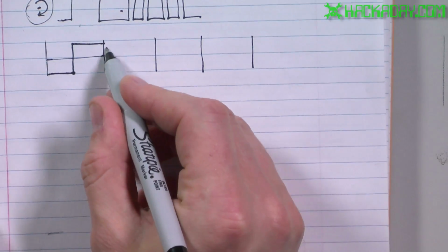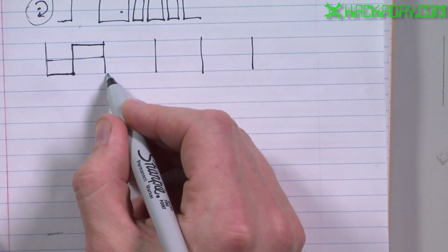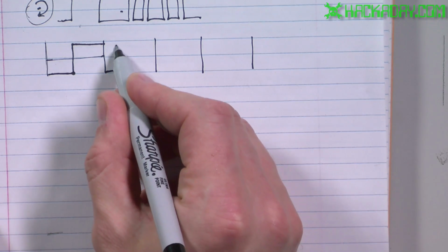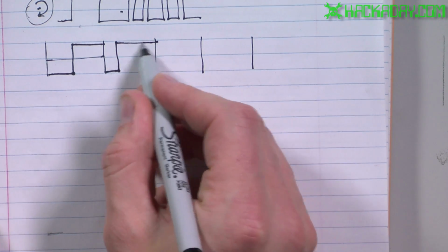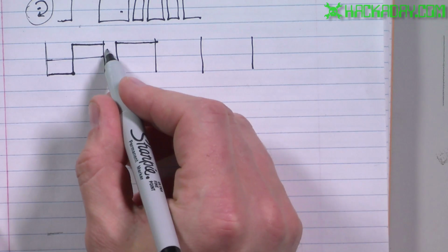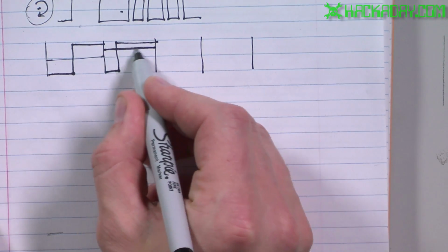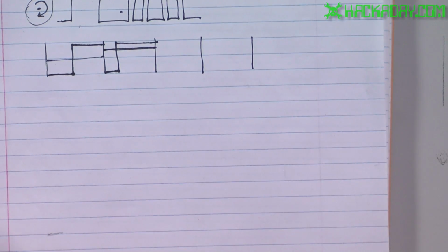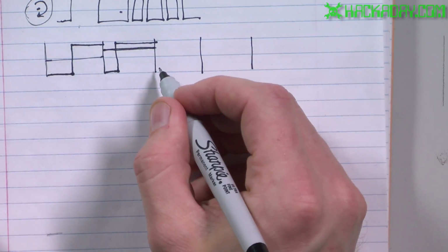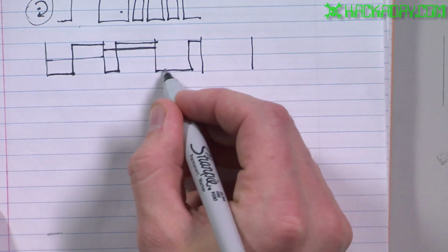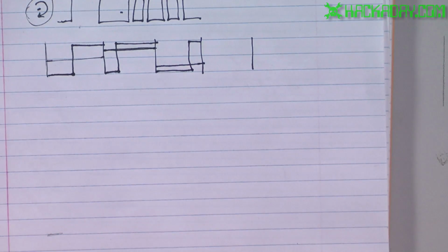If you wanted it to be 3/4 on, just like something like that. So it's on for 3/4 of the time and off, and the average will be up here then, if this is an analog voltage. And so on and so forth. You know, mostly off, be like that. The average would be way down here.